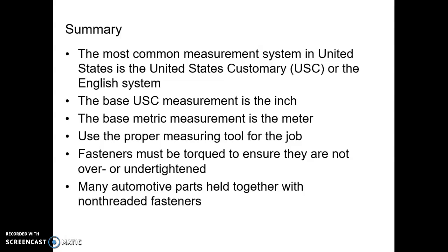Using the right tool for the right job, again, is important. We always have to make sure that we torque fasteners. They cannot be over-torqued or under-torqued. Many automotive parts are also held together with non-threaded fasteners.